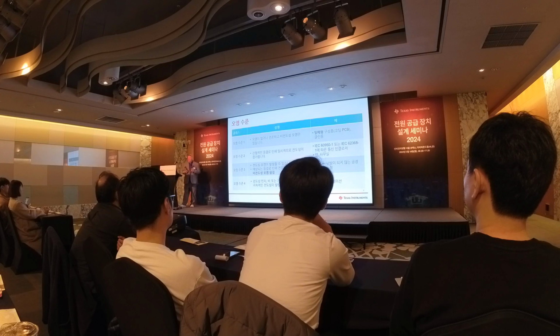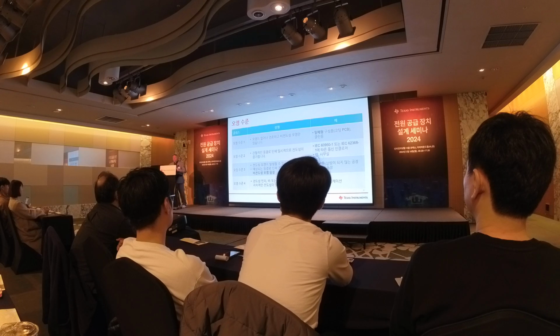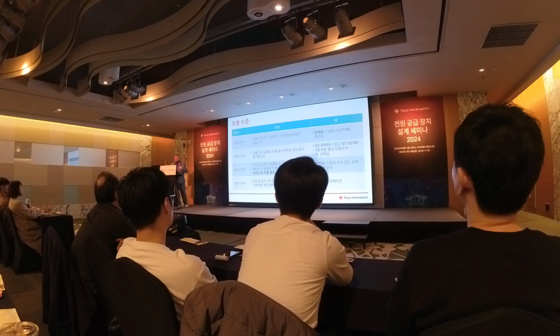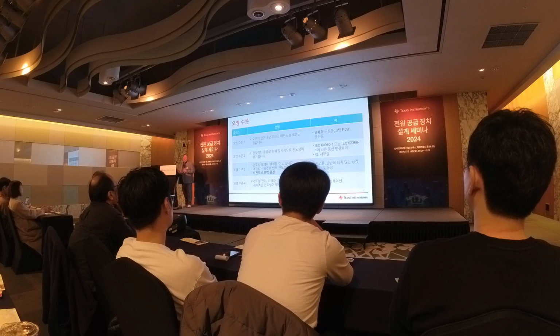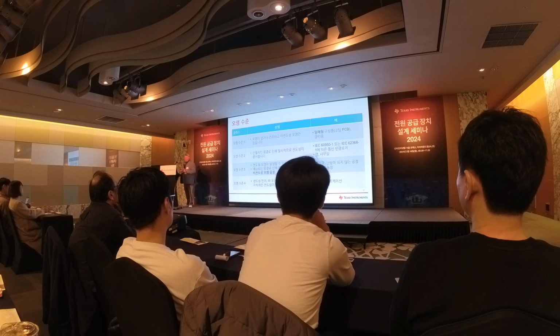Okay, the next important topic for creepage is the pollution degree. Now when I say pollution degree, I'm not talking about the air outside. We're talking about on the PCB itself, whether there is liquid or dirt or other types of things that are contaminating the surface of my system.